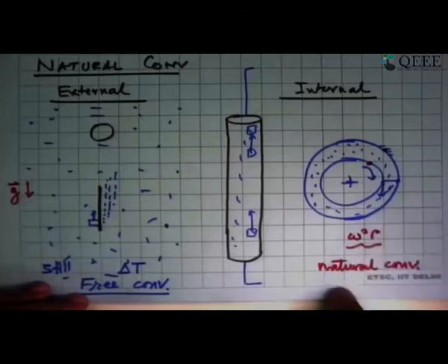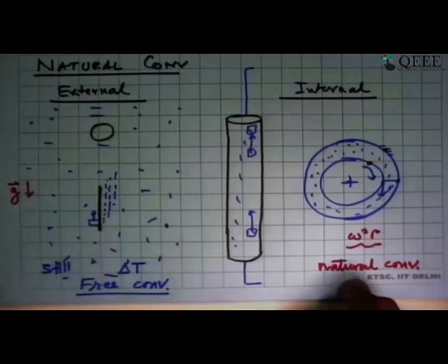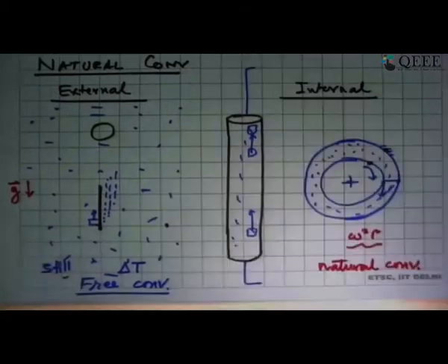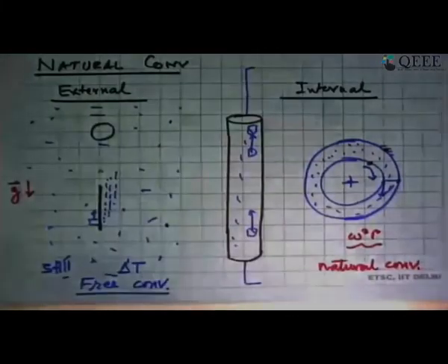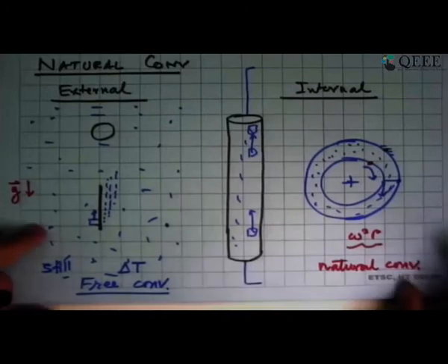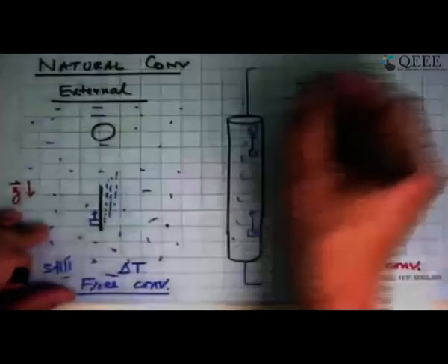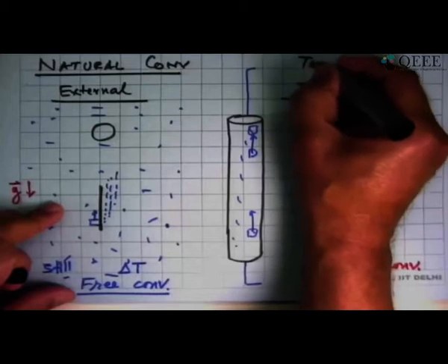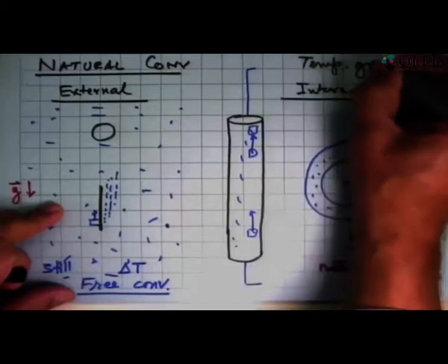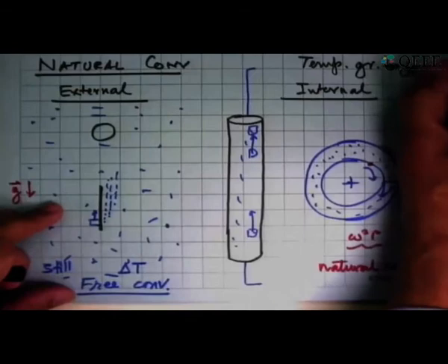They realized there is not forced convection taking place, but natural convection taking place, and because of that, heat transfer rates are much lower than what forced convection was predicting. And so now you have to redesign the device from a very different perspective so that temperatures remain within limits. So the important thing that we have seen here compared to the earlier case is that in natural convection, it is the temperature gradient that generates fluid flow.